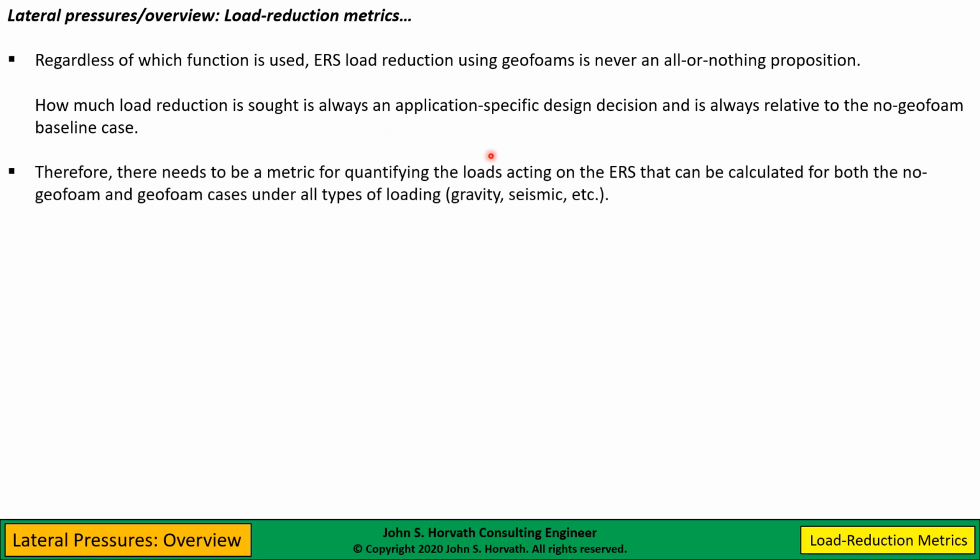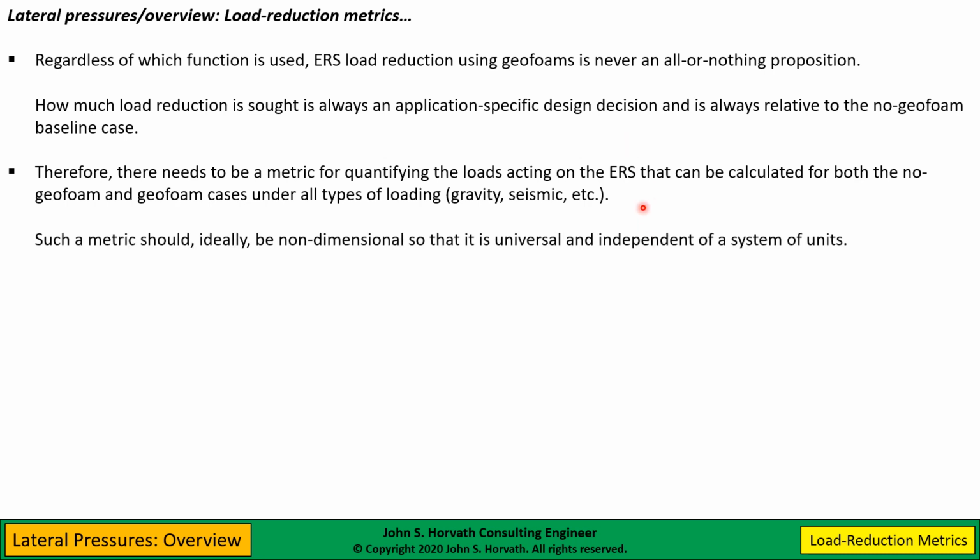So we need a metric for quantifying the loads acting on an earth retaining structure that can be calculated for both the no geofoam and geofoam cases and under all types of loading, gravity, seismic, whatever. Earth pressure, earth loads, surface live loads, things like that also. And this metric should be non-dimensional, so it's independent of system of units, and we can apply it universally.